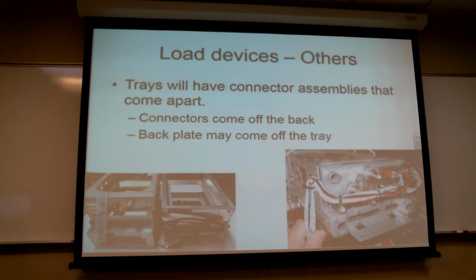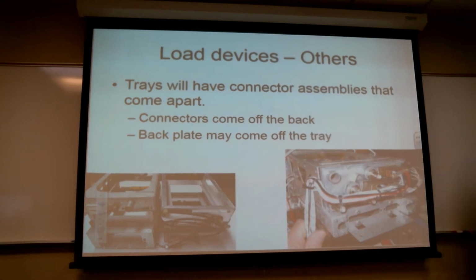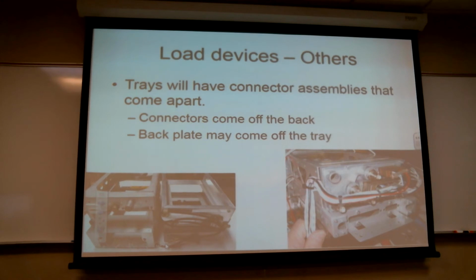Some of them are going to route like the black and red ones. I'm going to say that's a Garmin 430 tray. I might be wrong, but it looks like it. You're going to have these two going to your power and ground buses, your blacks and reds. Some of them will go off to an indicator head if you have an OBS or a GPS indicator on it.